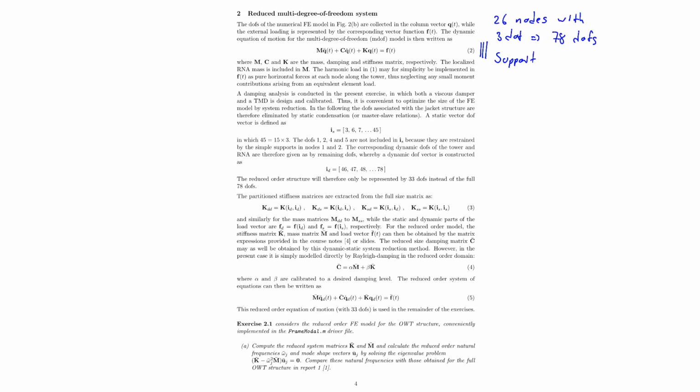that is the two transverse displacements of node number 1, that gives us DOFs 1 and 2. Number 3 is the rotation of node number 1, that is free, that's therefore not supported, and then we again support DOFs 4 and 5. So these 4 degrees of freedom we then support, and that leaves us with the remaining degrees of freedom as being free. But in this case, in this report, we are going to apply system reduction.